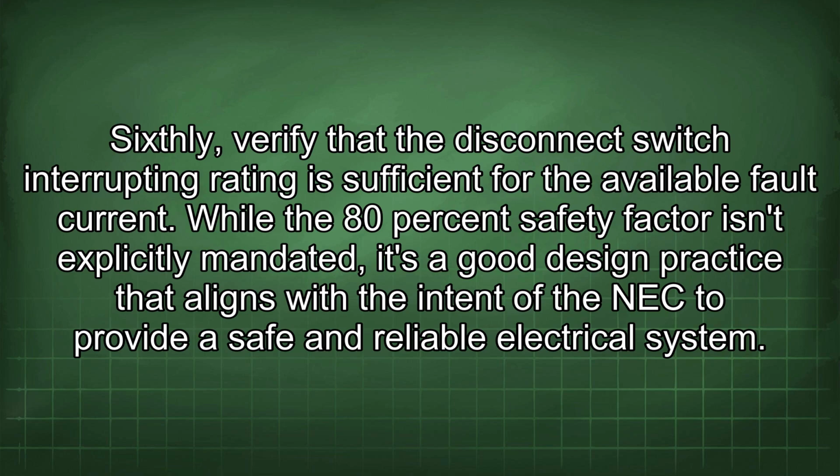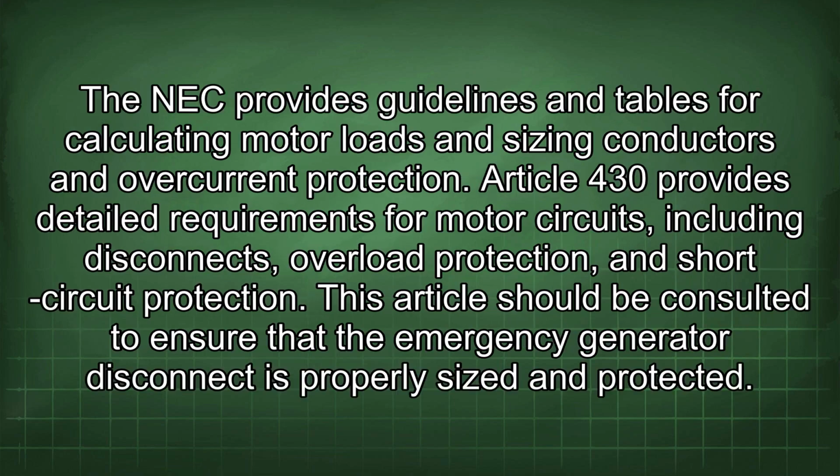While the 80% safety factor isn't explicitly mandated, it's a good design practice that aligns with the intent of the NEC to provide a safe and reliable electrical system. The NEC provides guidelines and tables for calculating motor loads and sizing conductors and overcurrent protection. Article 430 provides detailed requirements for motor circuits, including disconnects, overload protection, and short-circuit protection. This article should be consulted to ensure that the emergency generator disconnect is properly sized and protected.